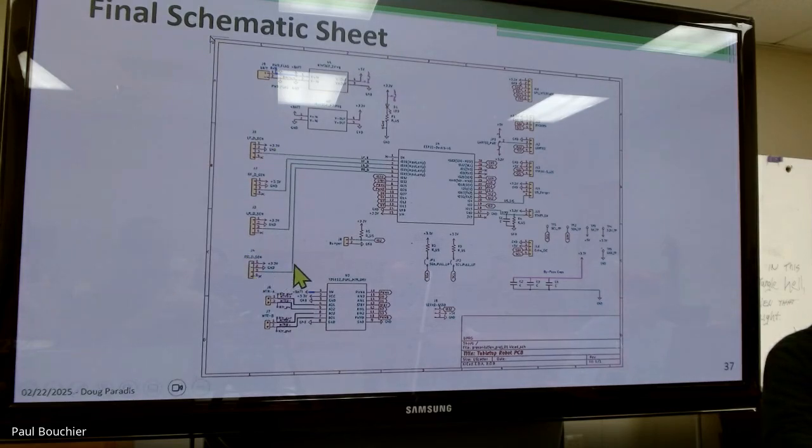Okay. This particular robot project has 4 drop sensors. It has a dual motor controller. It has an ESP32 devkit version 1, which is a 30-pin version. It has a couple of pull-up jumpers that are selectable with a jumper. It has one servo connector for an SG90. It's got its SPI bus split out, which I guess you could use for a display or something. It's got a BNO85 breakout, I2C. It's got, can't read this, UART. Okay, so it pulls out UART too.